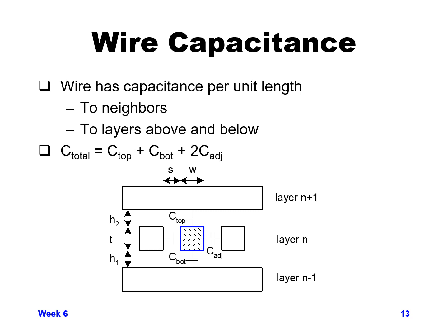Whereas in the width direction, you also have capacitance to your neighbors. For the wires adjacent to you on the right and the left, the minimum space that you're allowed in a given metal layer will be the same on either side. So the maximum capacitance you can have is C adjacent times 2, one on the left and one on the right of the wire that you're driving.